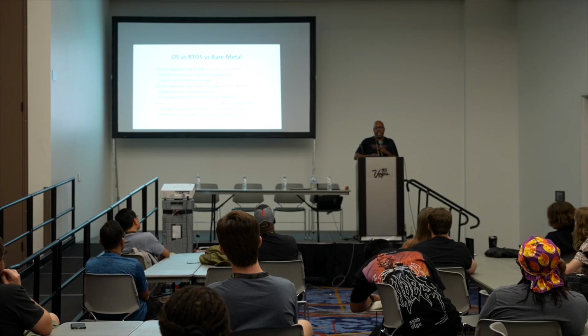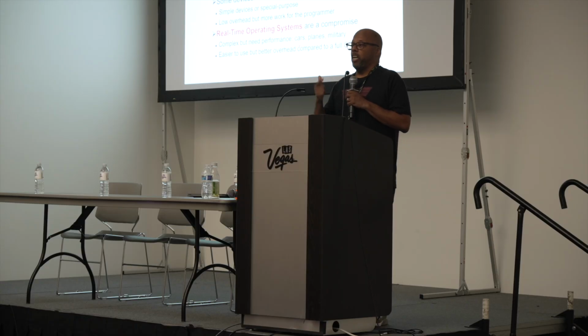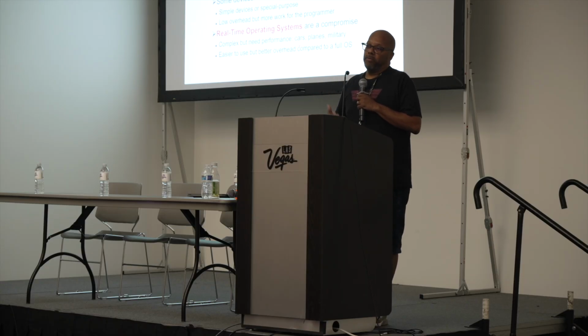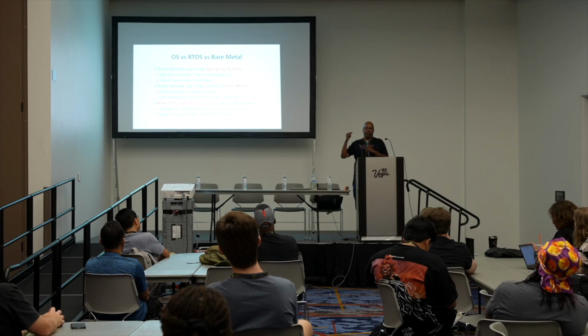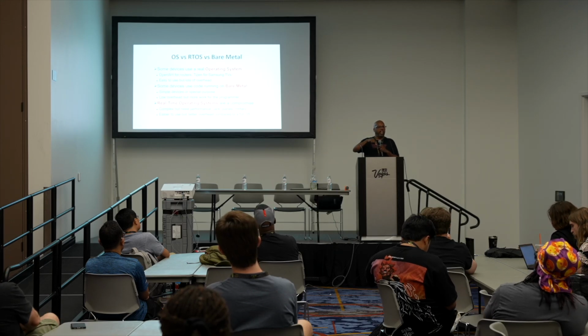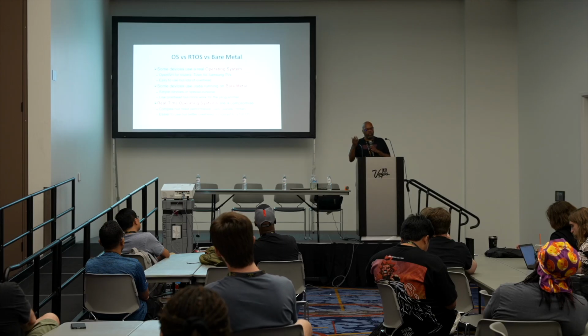So if you have some task that needs to be performed, like, I've got to sample this audio signal 8,000 times a second, and you've got to meet that deadline no matter what, a real-time operating system is the way to go because it'll make sure that it interrupts everything around that deadline. You know what I mean? So they have scheduling algorithms that they use to support that.